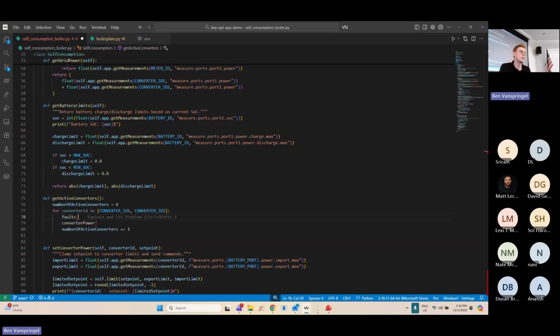And of course, we already have defined some of these constraints already, like the minimum and maximum state of charge. But minimum and maximum state of charge is only one. You can also look at the actual voltage of your battery as a second measure to make sure that you don't overcharge or over-discharge your battery. So looking at state of charge, looking at voltage is one, and so on and so forth. It's a controlled lab environment and getting to know the device.